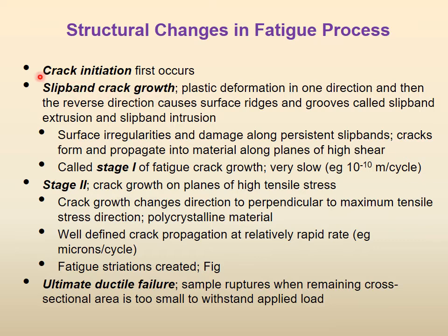Remember, from your material science, that materials have slip planes along which the material can deform more easily. So plastic deformation in one direction, and then the reverse direction, causes surface ridges and grooves called slip band extrusion and slip band intrusion. So you see there is a slip band, load is going there, but then it hits a grain boundary, and the direction may change.